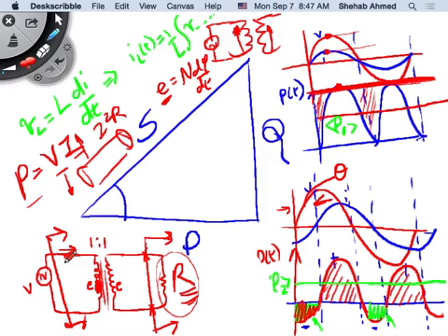And of course, eventually, if some of these turns are shorted, that means there's a local heating area, and it's not made for that. Again, these wires are insulated, and now you've broken the insulation, and now you're just adding lots of losses in this small area, and these losses are heating up the place and bringing down the insulation, and eventually it goes bad. So that can happen eventually, but the idea is this magnetizing current is set up by this magnetic field.